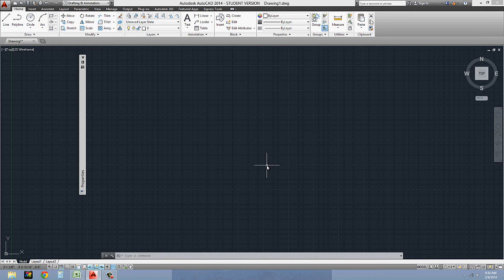They can be inserted as attachments and overlays, and we'll look at that in a second. And just remember, the other thing about layer 0 is that XREFs should be inserted on layer 0, or their own special XREF layer. This comes back to when we start to turn information on and off; it just makes it a lot easier. So this is the second thing, besides the original objects of blocks, that we should be putting on layer 0.